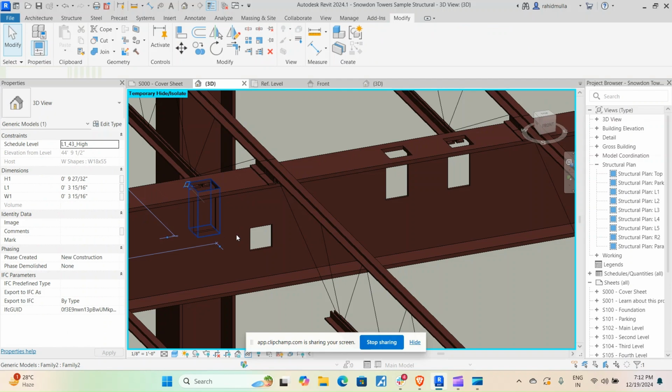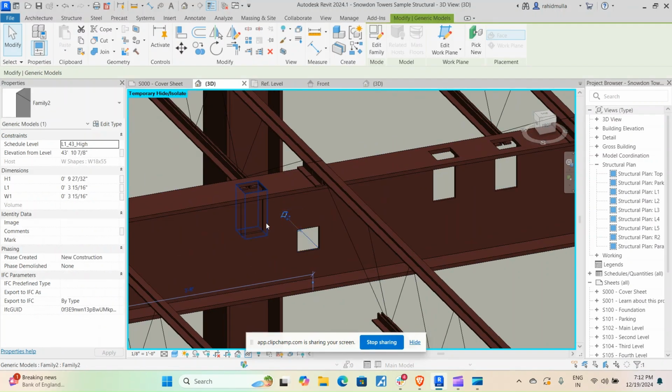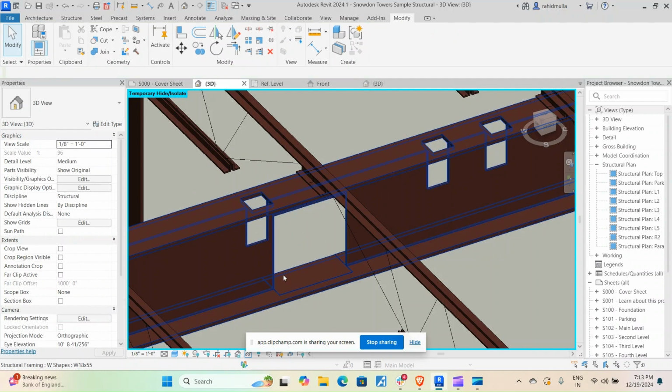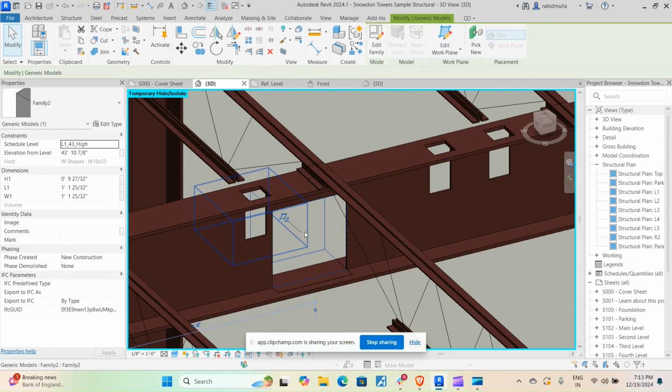Okay, so what we'll do is again we'll create similar. See, the reason it didn't cut in a proper manner here is that it has cut this family, but there isn't that much space for this family to expand. So we'll select this void, and we'll give 350 here, and 350 here also, in the sense 350 mm it has to be, and here also 350 mm. So see how nicely there is a cut of the length and width that we wanted.